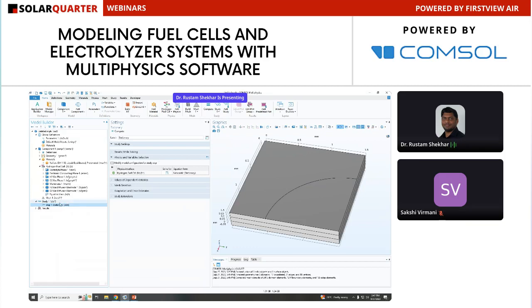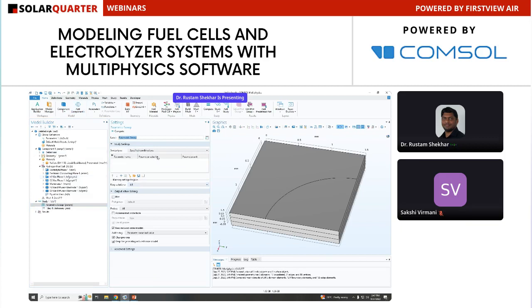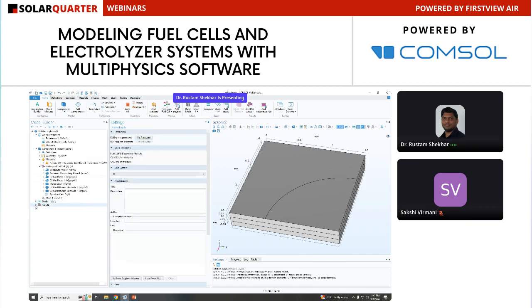study to it. So to get the polarization curve, I will just add the parametric sweep, and here I can specify the potential and sweep for that potential. So this is one basic setup which you can have and compare two different kinds of fuel cells.